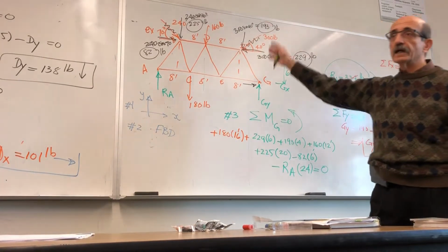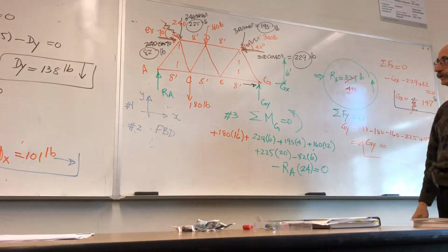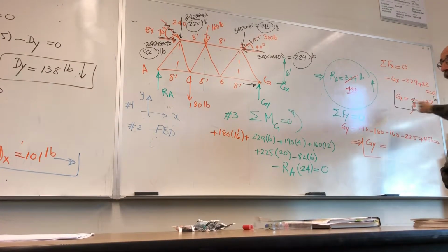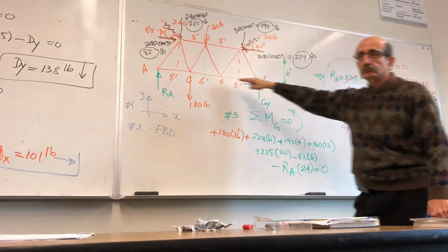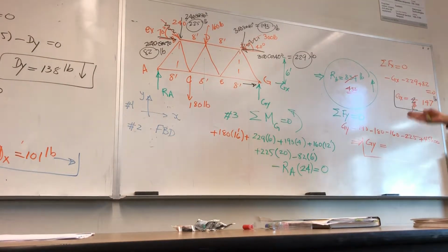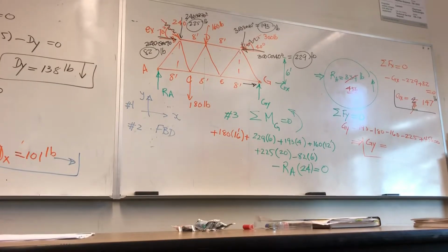So it gives you the angle, so you know where that is. But coming from where? Well, you need to find the resultant. Find the summation of forces along X, summation of forces along Y, right? So you can put it, say, along the X axis. So you find the magnitude, right? And then you have all the forces. If you have the summation of force along X and Y, then the square root of the sum of the squares will give you the magnitude.